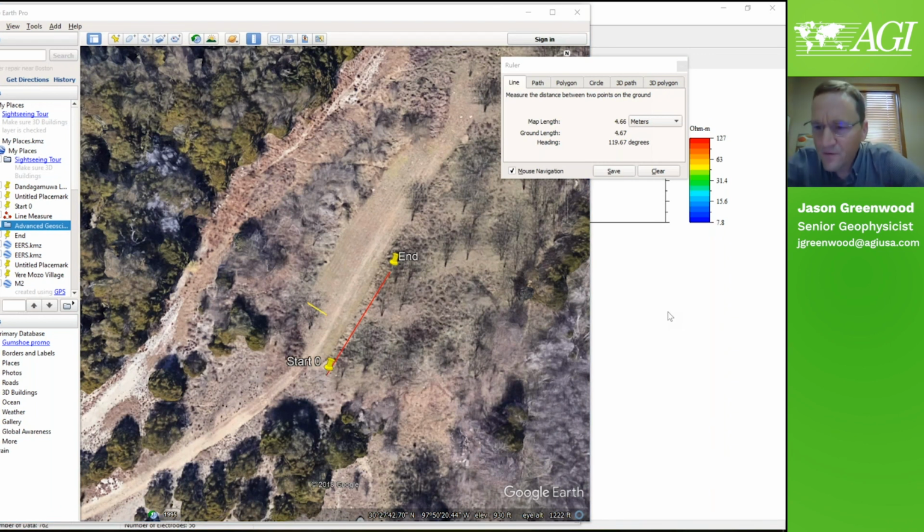Is rebar in concrete pavement enough to impact parallel resistivity lines? That's a tough question because sometimes the rebar is all tied to each other in a grid. So if you imagine a metallic mesh, even though concrete is resistive, that makes the concrete overall very conductive.